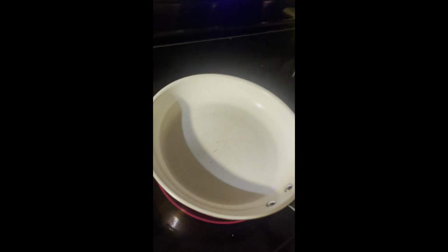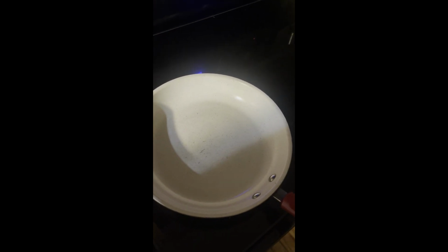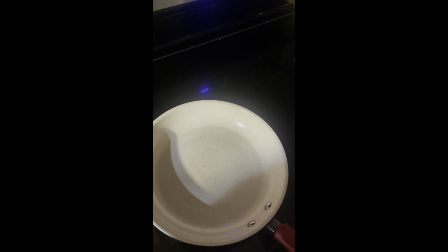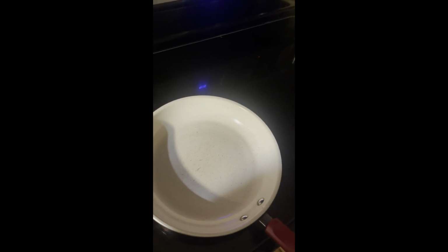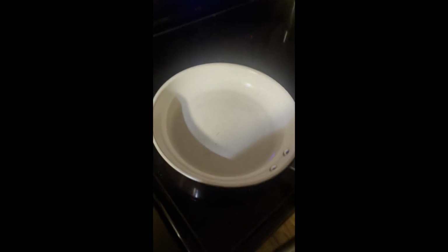In the experiment, a pan was put on the stovetop, turned up to the highest setting, and allowed to equilibrate. The aluminum sheet was then put under the pan. It was done this way so the top side was not exposed to the environment. After a few minutes, the aluminum was removed from the heat source and the temperature was measured with a temperature probe. A timer was started before the data collection so that no time was wasted trying to start the timer during the experiment. T-infinity was collected beforehand.